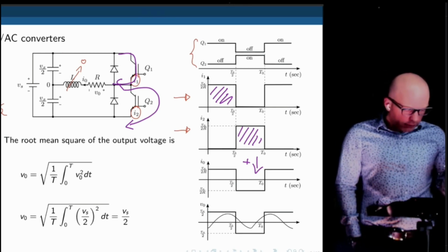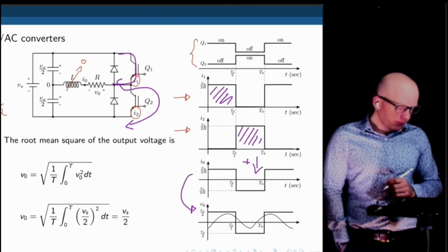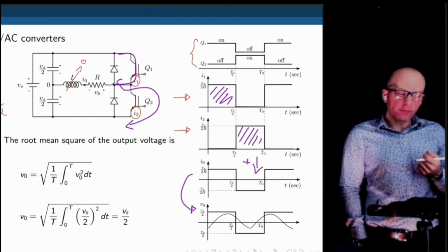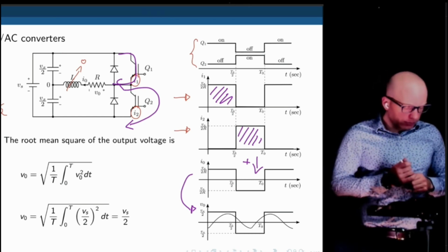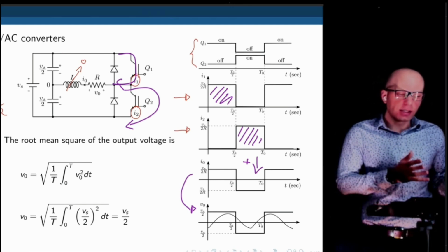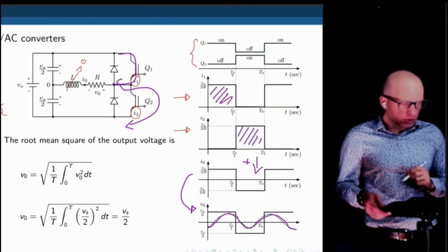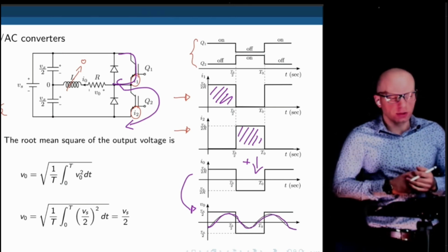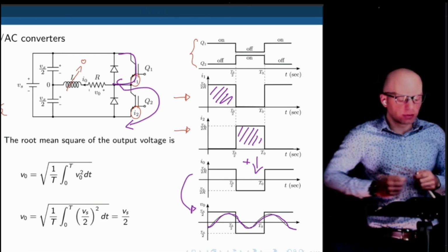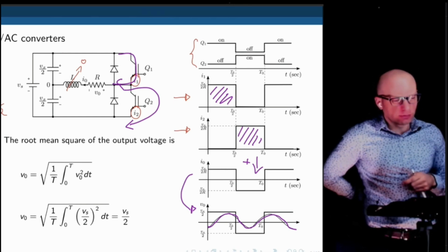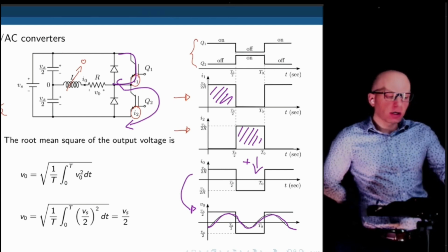This will result in a voltage applied to the load that will follow the current for a resistive load, something square like that. But if we had, say, an inductive load, things would be a little bit different because current cannot change instantaneously. So the actual voltage that we would see appearing across the load would be something like that, because of the effects of the inductor that can store energy and send that energy back to the power source. So this would be the effective voltage across the load. It's not a perfect reflection of the current.